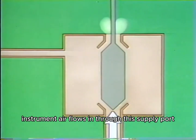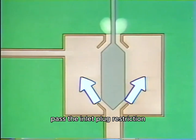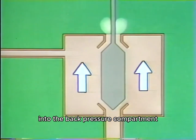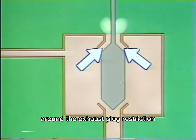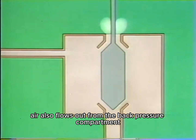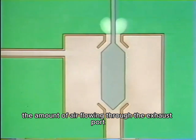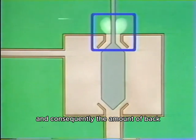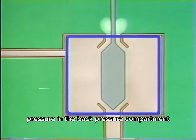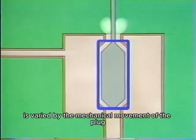Instrument air flows in through this supply port, past the inlet plug restriction, into the back pressure compartment, around the exhaust plug restriction, and out the exhaust port. Instrument air also flows out from the back pressure compartment through this output connection. The amount of air flowing through the exhaust port, and consequently the amount of back pressure in the back pressure compartment, is varied by the mechanical movement of the plug.